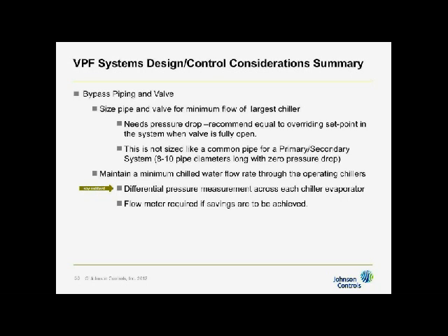Let me rephrase that again. When I'm at 3,000 GPM, I'm at 20 feet of pressure drop. But when I drop all the way down to 776 GPM, the minimum for this chiller, I'll be at 1.2 feet. Now try to find some pressure sensor that you can control from that can monitor and measure that level. So you end up having to set your minimum flow much, much higher so you don't drop below dead bands and so on. So it is a much more accurate system to use the flow meters. You can go to lower flows so that when you are in bypass, you're not wasting as much energy.